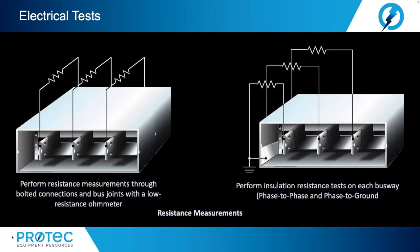Now, during this webinar, obviously by the title of the webinar, we will be focusing on resistance measurements. And when we really are looking at the resistance measurements on the busway, as we see, they fall into two different categories. For instance, we see perform resistance measurements through bolted connections and bus joints with a low resistance ohm meter. So in this resistance measurement, we're really focusing on continuity of the circuit, how well it's going to pass current, or we're looking at how low the resistance is along the current traveling path.